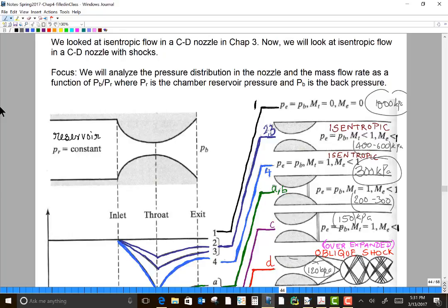What we really talked about is we integrated all the material that we have learned in the earlier chapters, and we looked at what happens when you have a converging diverging nozzle connected to a reservoir. This was very similar to what we did in earlier chapters, precisely Chapter 3. The reservoir has a standard reservoir pressure PR, which also happens to be the stagnation pressure for this flow through the converging diverging nozzle.